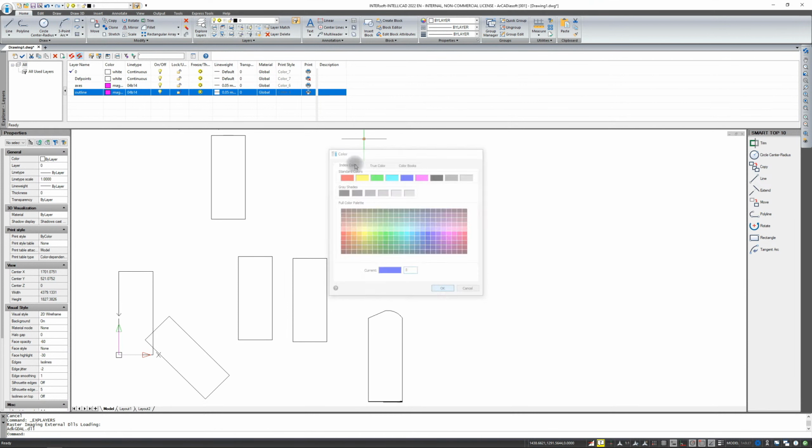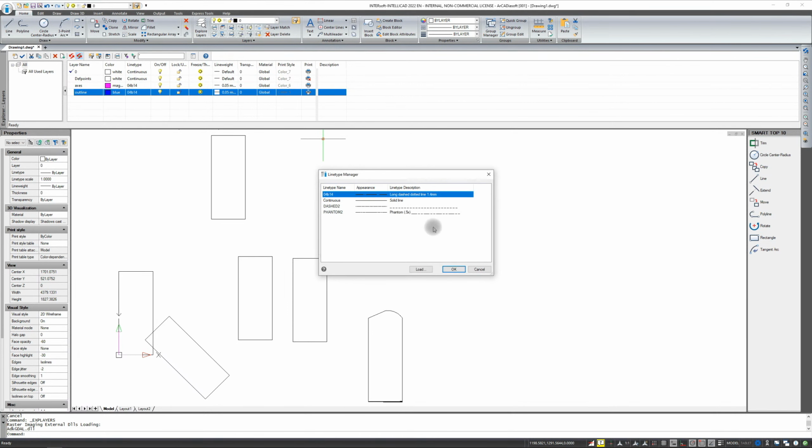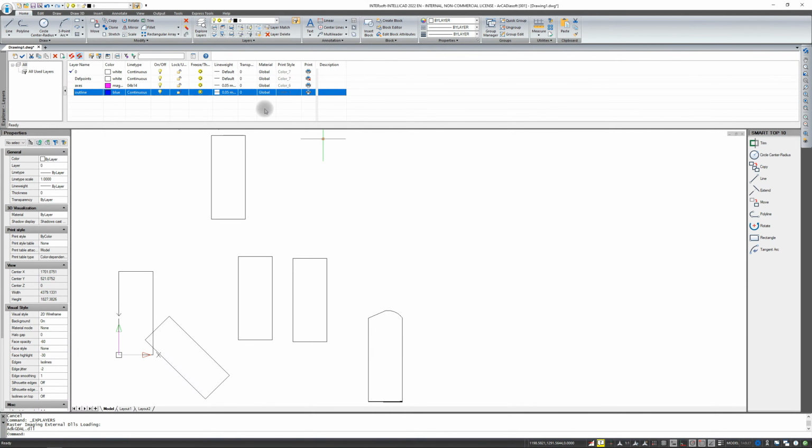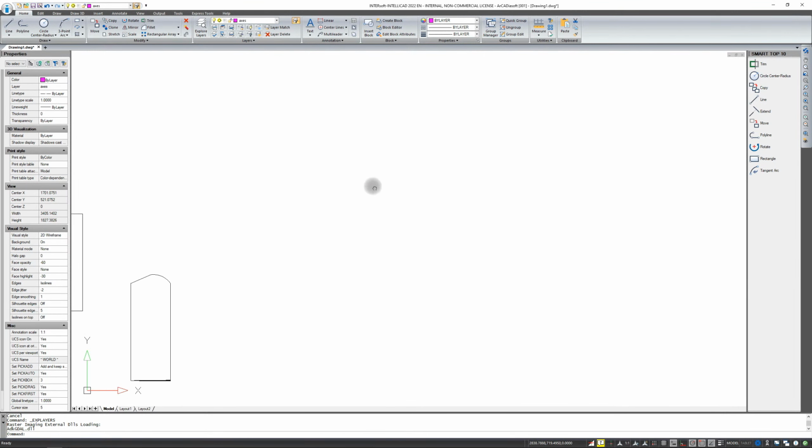It will definitely be elements drawn with a continuous and thicker line. I have the thickness turned off down here in the status bar. In the status bar, there's an option to turn the thickness on and off, but I have it turned off. But if there was such a need, you can turn it on at any time. Now the layer that will be active, which means the one on which I'll be drawing. I double-clicked it. These will be the axes.